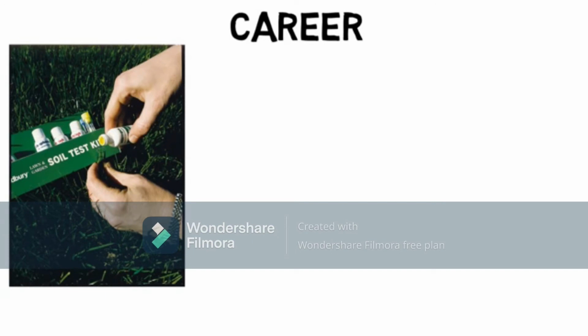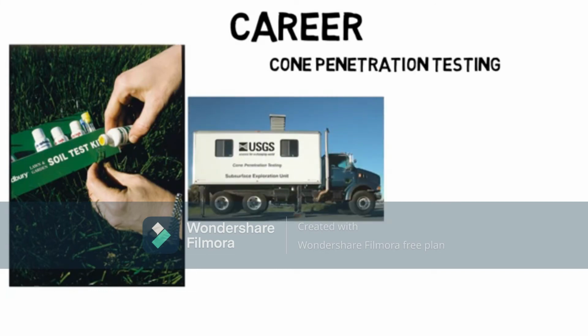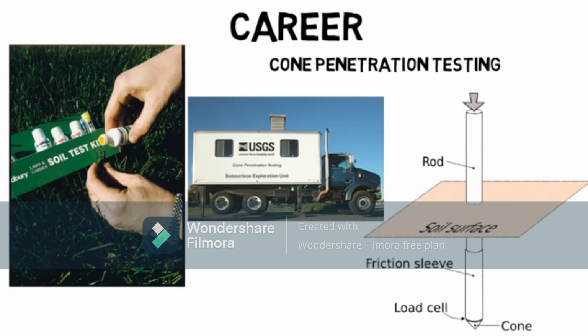One of the most used tests right now in this field is cone penetration testing, where a large truck goes out to the field which has all this equipment on it, and a cone is pushed into the soil, and the pressure will be monitored by a computer on the truck as it moves through the soil into the earth. Based on the pressure, you can analyze the soil mechanical properties.